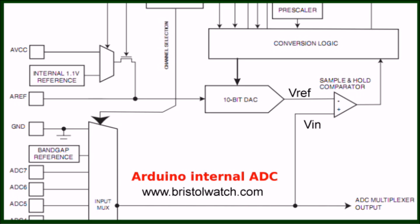This is a partial snapshot of the internal workings of your Arduino microcontroller, that is, the ATmega 168 microcontroller in this case. What do we have here? This is how your analog to digital conversion works. All right, what do we have here? We have an analog multiplexer. Here are your analog to digital inputs, wherever they are. It's fed to VN, there you go, sample and hold comparator. Whatever the voltage is there. Now what you have is conversion logic.